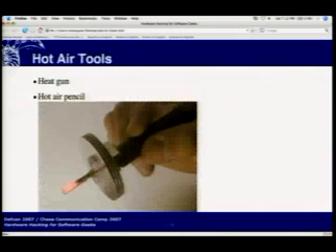Cool. This is a home-built hot air pencil. You can get hot air guns pretty easily. They're temperature controlled, usually 600 to, say, 1,600 degree stream of air, capable of melting solder. This is useful when you're trying to rework a surface mount board. You just apply the heat, heat up all the pins of the chip at once, and you can just lift it off with tweezers, which is a lot better than trying to get each pin a single one at a time with a soldering iron.